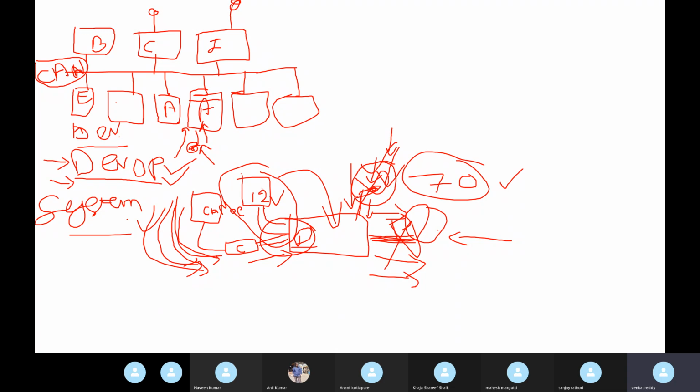Next, in parallel, vehicle level testing will happen. In the vehicle, we also flash the code, the merged code that the DevOps team gives, and test all the functionalities. This is the system engineers' work. Next comes vehicle level testing. Generally, vehicle level testing happens in Europe and the US, where cars are developed, like Benz and those. In the vehicle, we place the ECU, whatever ECU is under development, and we flash the code and start the testing.